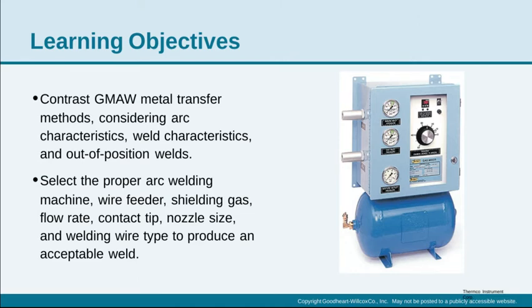I might have a few different types of wire out there. I can show you the difference between an .045 weld and an .035 weld. We have two kinds of gas. I have a little bit of argon, oxygen left, so I might get into spray welding. I don't know. It just kind of depends.